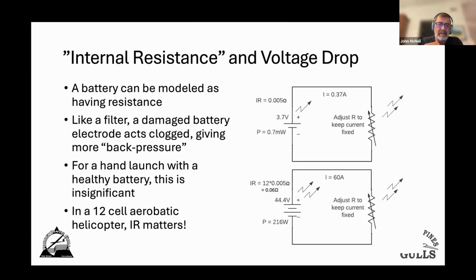Pay attention to your battery health. If you are flying electric power and you notice they're warmer when you land, or this is important, every time you charge, check the relative per cell voltage when you plug it into the charger. If when you land and you recharge, you're starting to see the 3 or 6 or 12 cells not all being within half of a tenth of each other, you're starting to have a cell go bad. That's the easy way to do it. But again, whole other talk. So internal resistance clear?